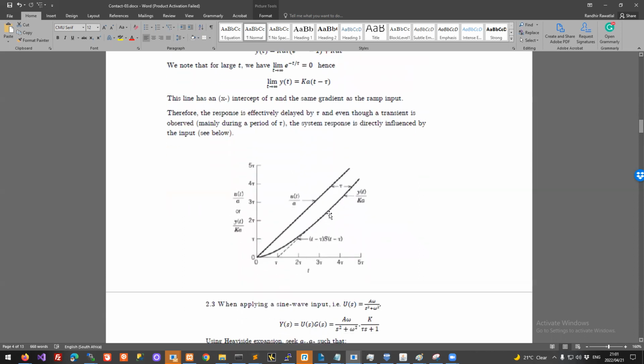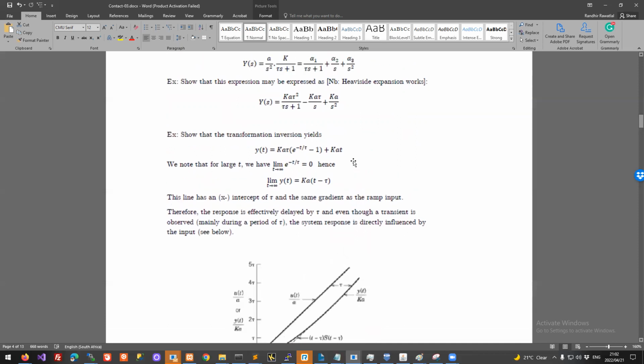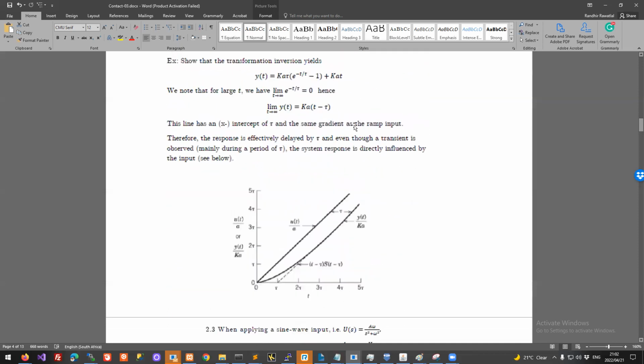Eventually, it becomes a straight line like this, and you will go through a transition period where it smoothly transitions from the 0 to that new line. So you've applied a ramp function. So that's your input. You've applied a ramp function, and then your process slowly moves away from the steady state it was at, and then it keeps increasing with the increase of your manipulated variable. So that is something we could have anticipated.